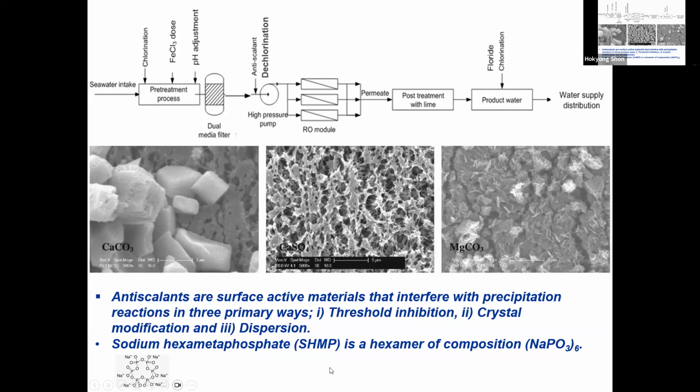So that's the anti-scalant. When you design your seawater desalination, depending on your recovery and your process design, you will have a warning sign in your software. In this case, you need to add this anti-scalant to reduce the overall scaling issue in the reverse osmosis membrane.